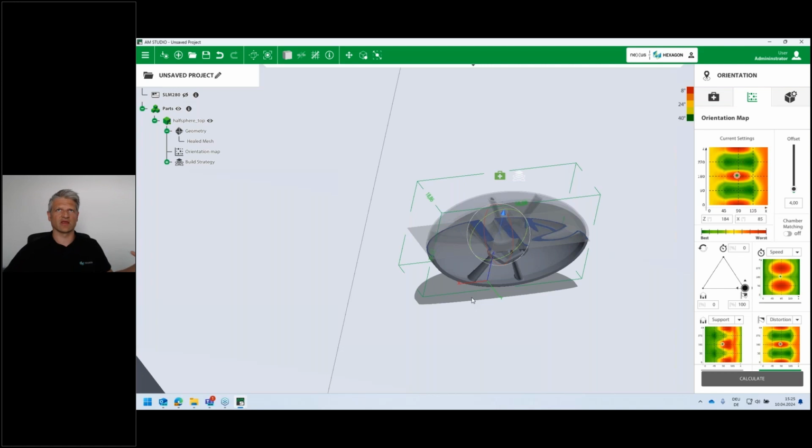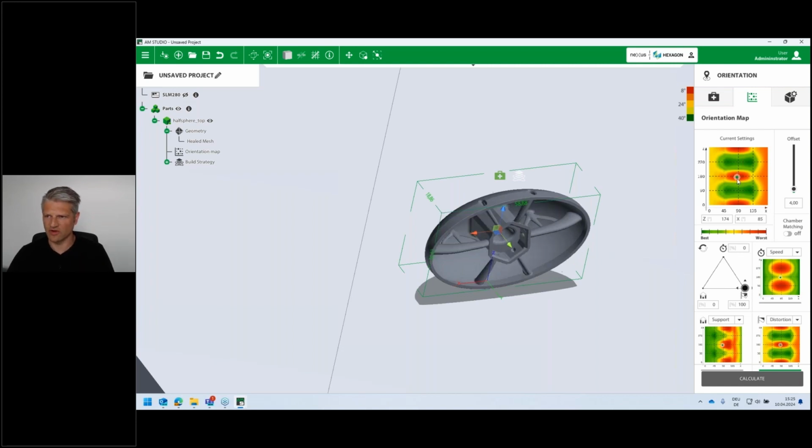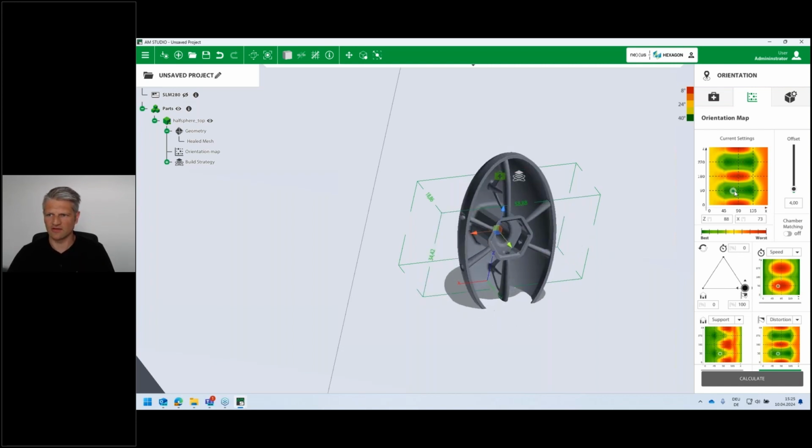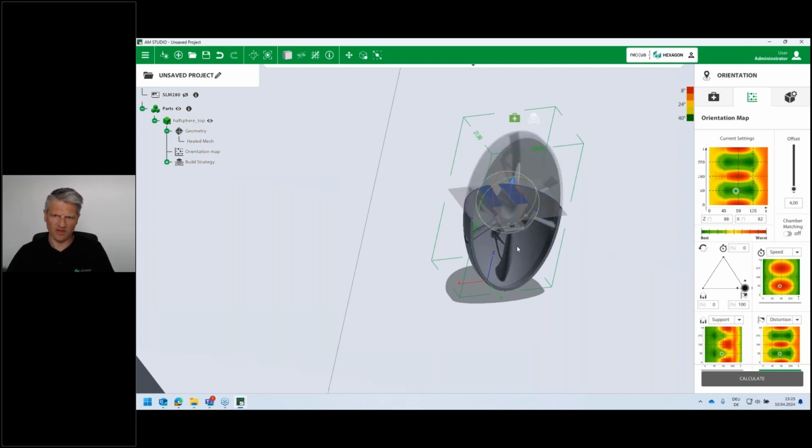When you have a big expansion in the X and Y direction, you have to deal with more stresses due to the shrinkage of the part. This can be seen pretty well here. The red orientation indicates a big XY expansion of the part. In comparison to that, this green orientation is also a very homogeneous buildup, but with a much smaller XY expansion of the part.